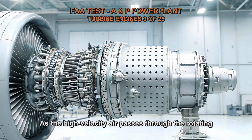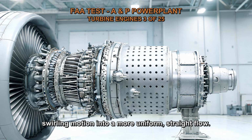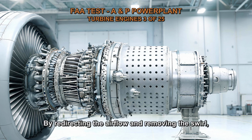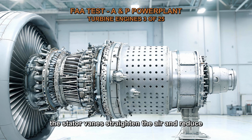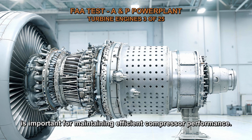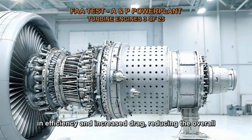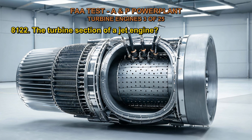As the high-velocity air passes through the rotating rotor blades, it acquires swirl or rotational motion. The stator vane assembly helps to convert this swirling motion into a more uniform, straight flow. By redirecting the airflow and removing the swirl, the stator vanes straighten the air and reduce turbulence. This straightening function is important for maintaining efficient compressor performance. Turbulence and uneven flow can lead to losses in efficiency and increased drag, reducing the overall performance of the engine.